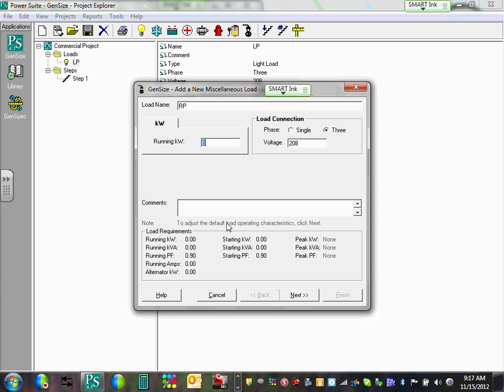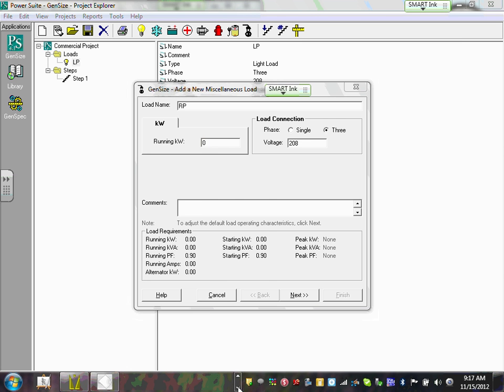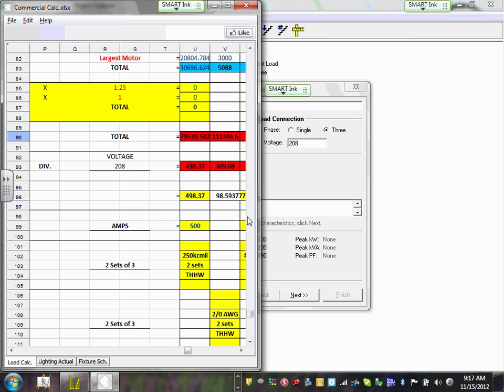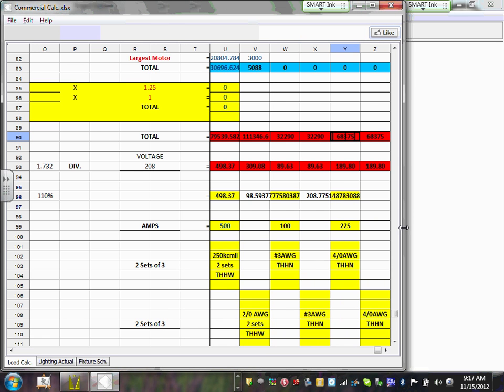Now I'm going to find the actual size in kW or kVA. Don't worry about kW, use kVA here. So I'm going to go to my friend. Who's my friend? Jeff, can you tell me if this 32,000 is yours? Am I looking at the right one? Okay, it's for Jeff, the receptacle panel size that you sized. Jeff came up with 32. If yours is different, don't worry about it. It shouldn't be substantially different. But if it is, don't sweat it too hard. So I'm going to use 32.